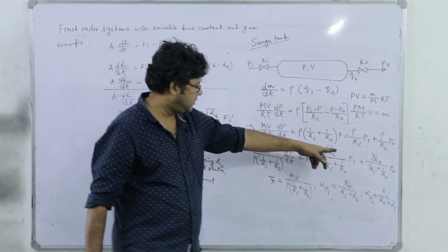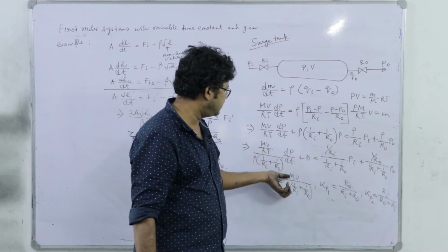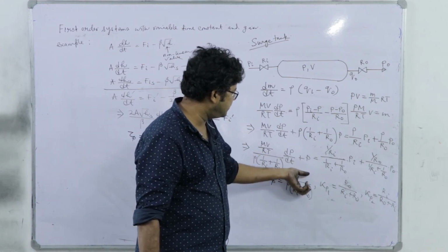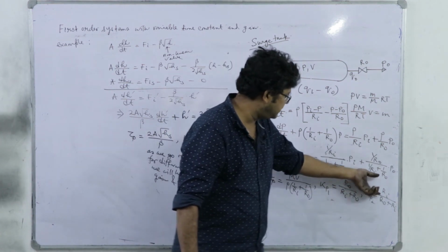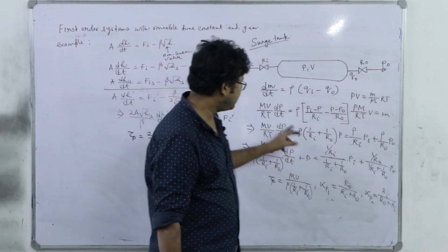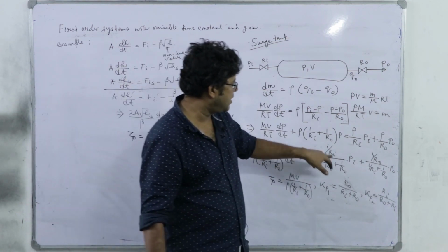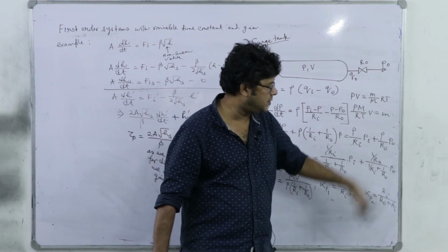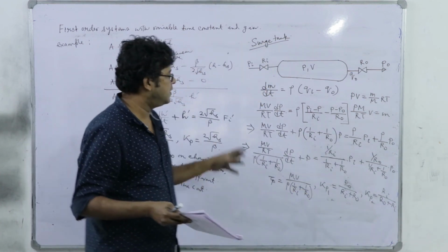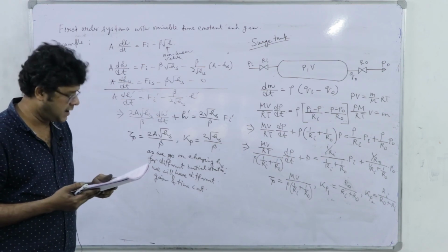Definitely it is there, but once we write the steady state equation, dPs/dt which is 0, plus Ps equals the Pis term plus this into Po. If you subtract, the last term will cancel out and we get the deviation variable form: dP'/dt, here P', and this constant into Pi'; the Po term is dropped. As a consequence, we have the typical first order system with one input and one output.